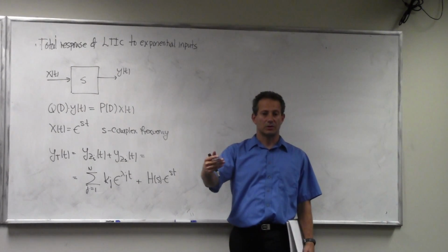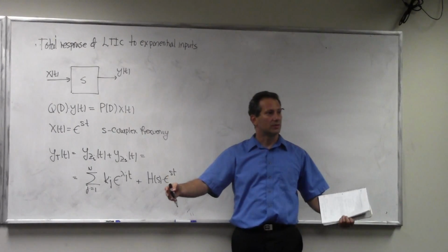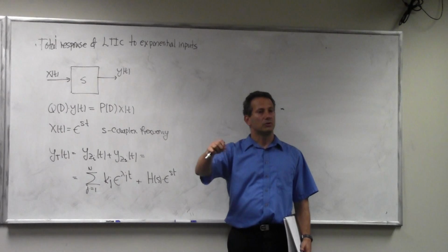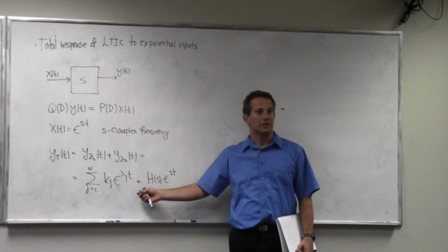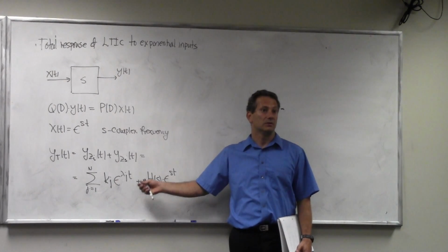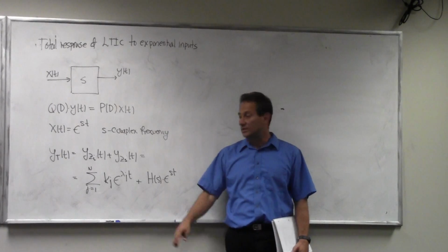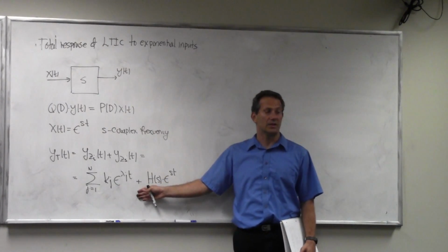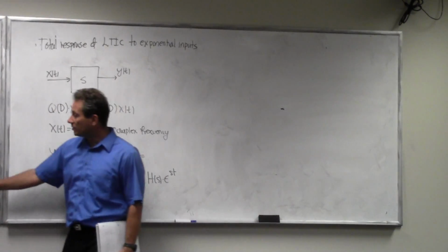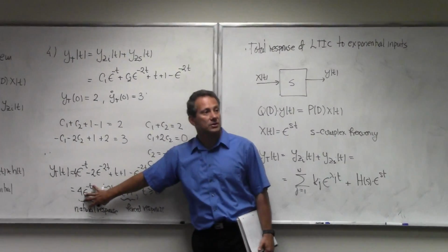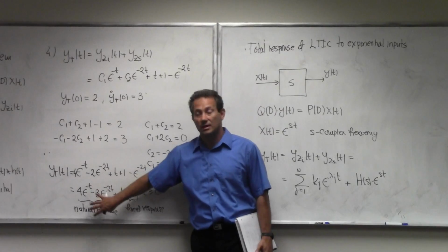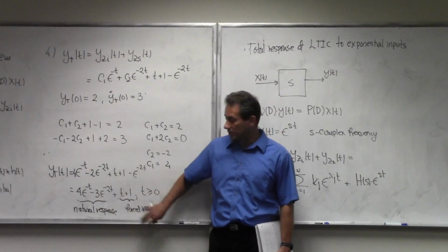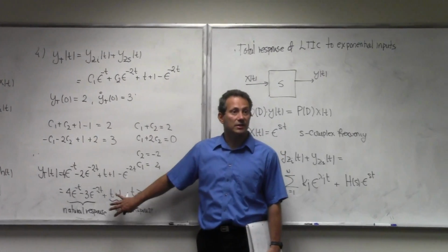You turn the circuit on. Initially, there's all sorts of transients happening, but eventually, at every single node, you're going to get something that is a sine or a cosine, right? It will look periodic as if these transients never existed. We're talking about a steady state response in that case. These are the natural responses, transients, they will die away, and then what is left is your forced response or steady state response.